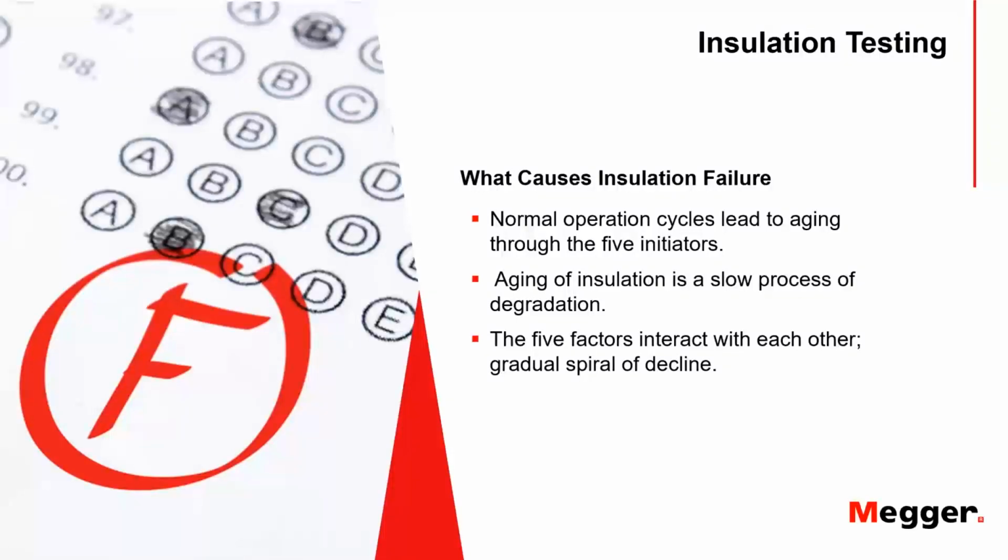So these problems feed on each other. For instance, at time of manufacture, you can have a tiny void somewhere in the insulating material. And during operation, that's going to arc across, that's going to keep arcing. And eventually you start to get a burn track. And then the burn track attracts more leakage current. And then over time, that breaks through the ground and takes your equipment out.